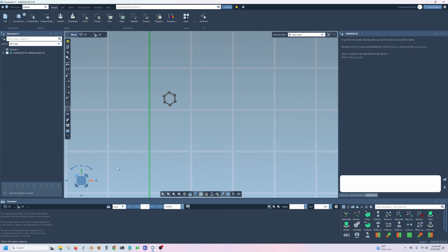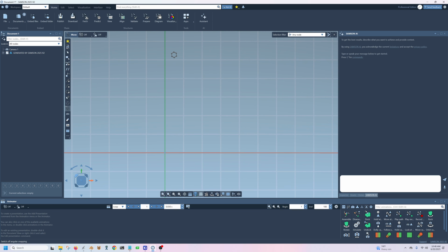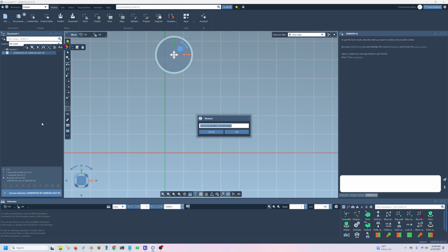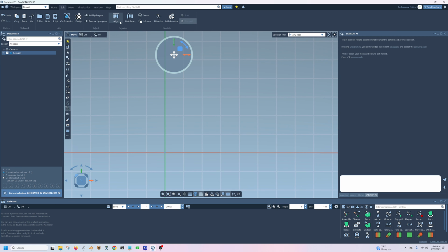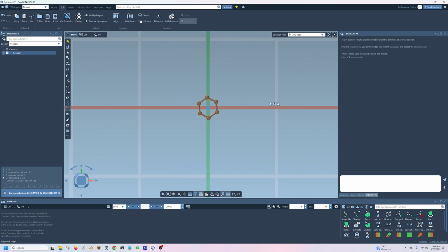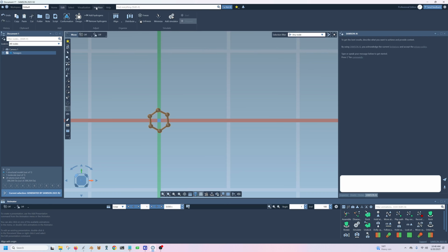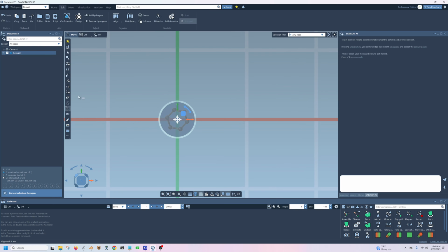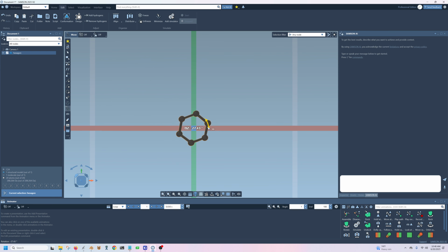So to start, let's center it up. Let's rename it to start. We'll just call it hexagon, and then let's go into the edit mode and we'll go align. Let's align it with the origin, and just to be extra sure to help us out with the extrude operations, we'll go align with z-axis like that. Keep it selected, and then next thing you want to do, I've turned on the move widget, so let's rotate it in z so that any edge is perpendicular to x like that.